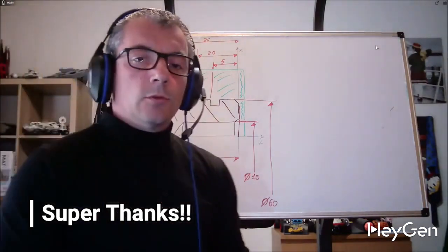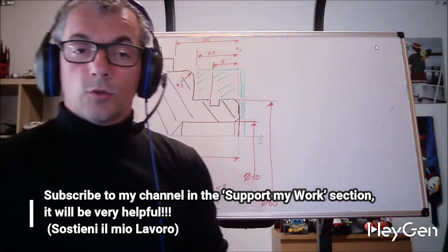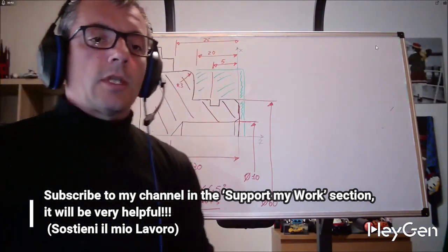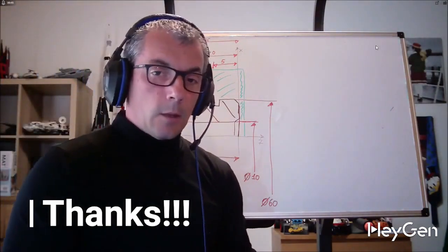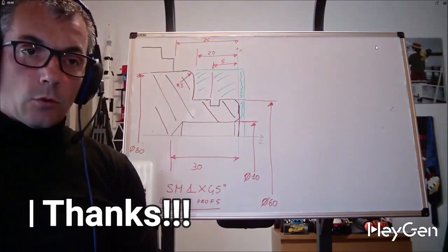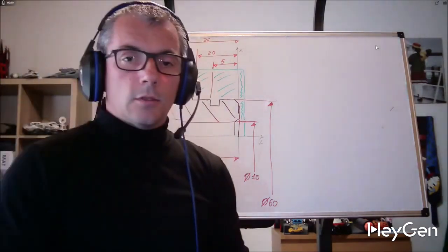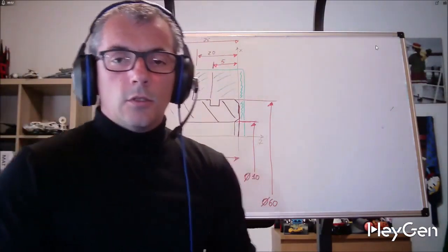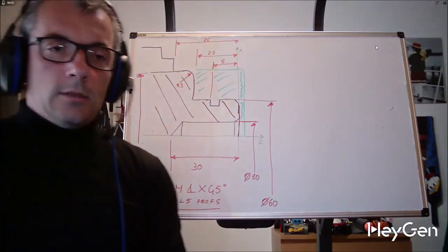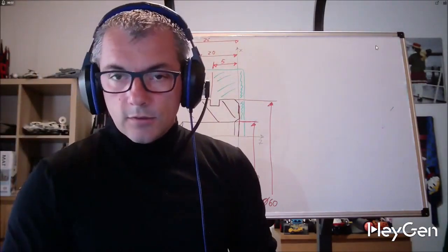We know how to make chamfers, and we know how to make radii. We have recently discovered that we can correct our profile to make it exactly uniform with the drawing by adjusting the tool radius correction. I tell you that outside of threading.